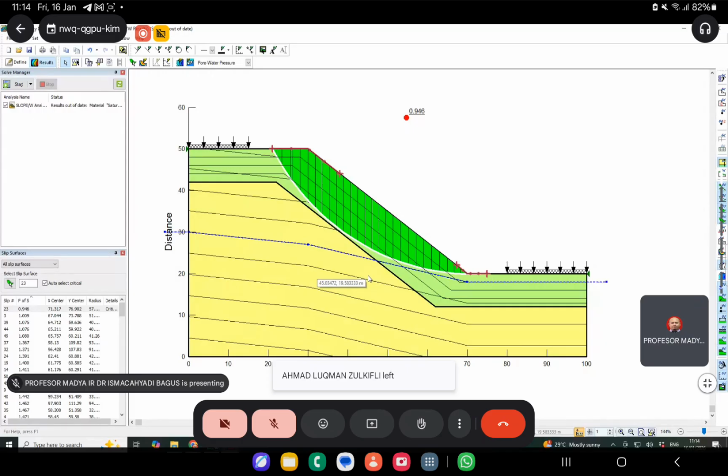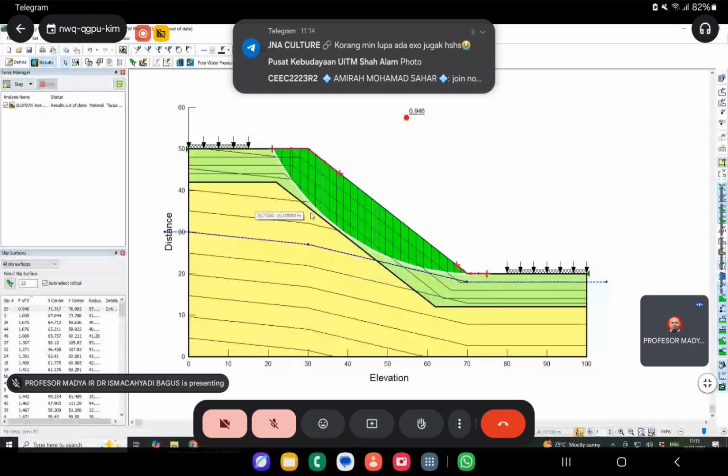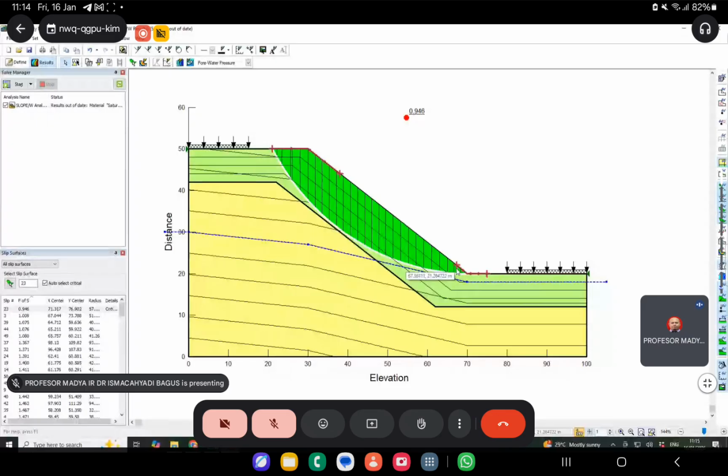All right, so how do you do this? You increase the unit weight of the soil from bulk unit weight to saturated unit weight. This increases the weight within the slip circle. Initially, you have apparent cohesion C. When it becomes saturated, we assume that suction diminishes and C prime becomes almost zero, so we put a zero value there.